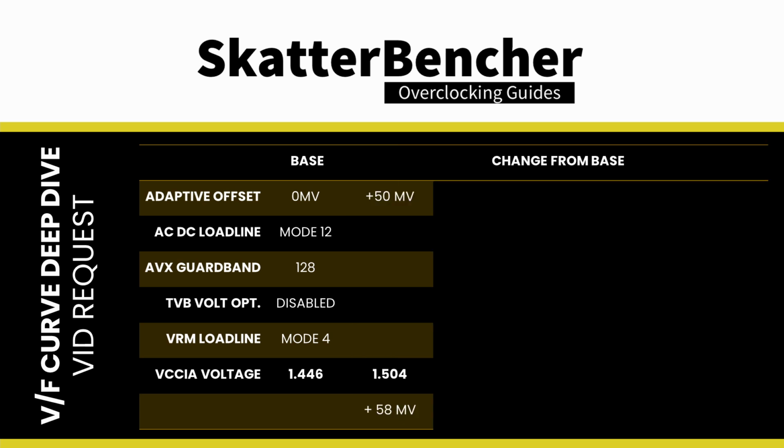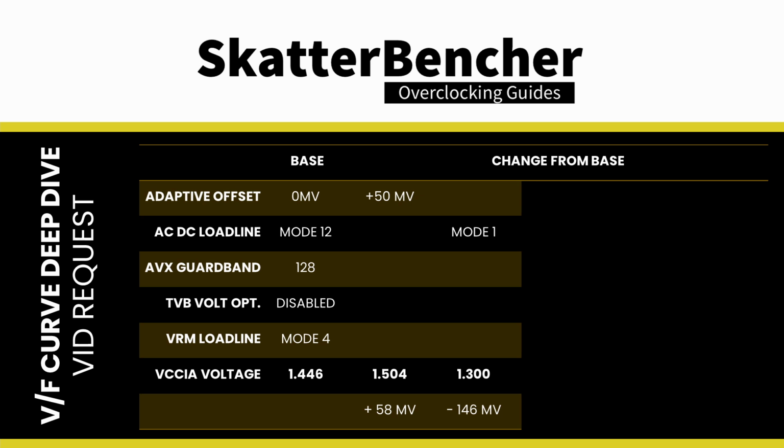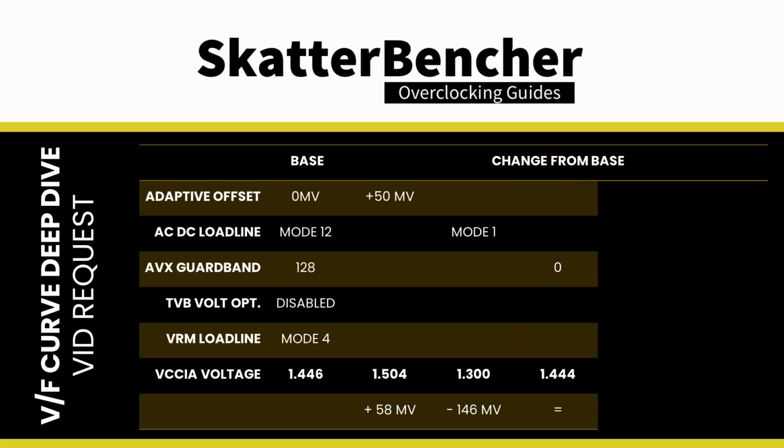When we add a plus 50 mV adaptive voltage offset, we see that the voltage increases to 1.504 volt. When we change the AC-DC load line settings from mode 12 to mode 1, the voltage decreases to 1.3 volt. When we change the AVX guard band scale factor to 0, nothing happens. That's because the BIOS doesn't run AVX instructions, so the guard band isn't active.